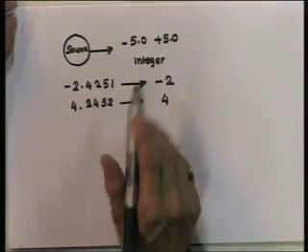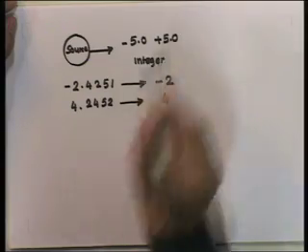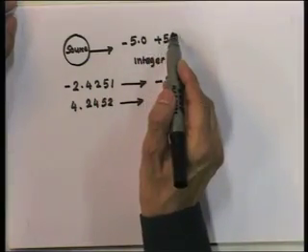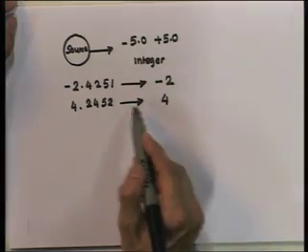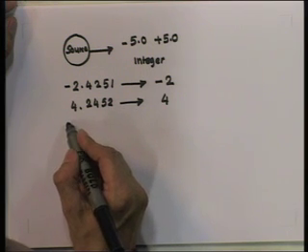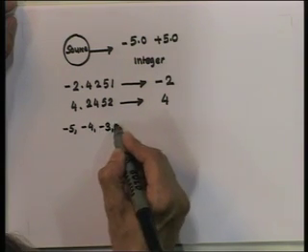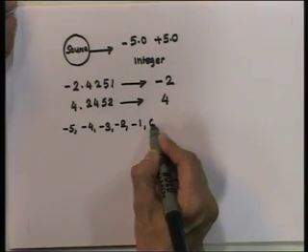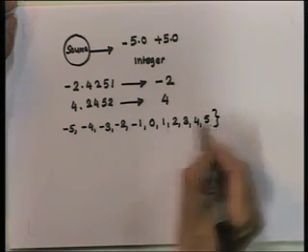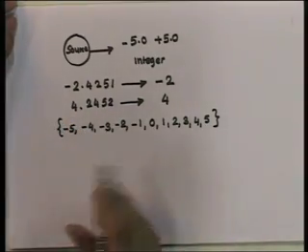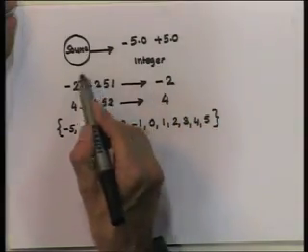This approach reduces the size of the alphabet required to represent the source output. The infinite number of values between -5 and +5 are represented with a set that contains only 11 values: -5, -4, -3, -2, -1, and so on. At the same time, we have also forever lost the original value.